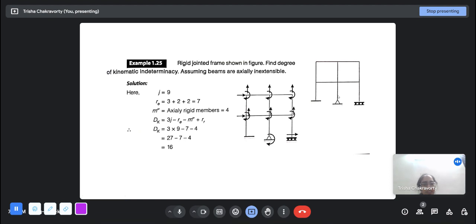And now the support reactions. So fixed support gives 3 reactions, hinge support gives 2 reactions, and this is a different kind of support that you may not have encountered before. This is a roller with 3 wheels. A roller always restricts the vertical deflection, so Fy it will give, but this also restrains the rotation.